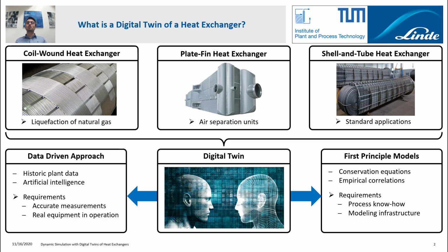The second approach one could go for is the development of a first principle model as the core component of the digital twin of the heat exchanger. It is based on conservation equations of mass, momentum and energy and on empirical correlations for heat transfer and pressure drop. The basic requirements are of course a large amount of process know-how and a suitable modeling infrastructure to formulate